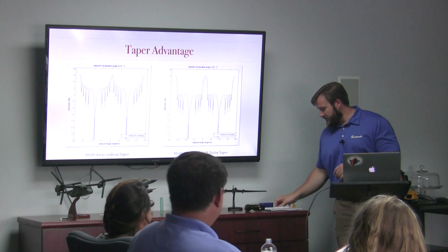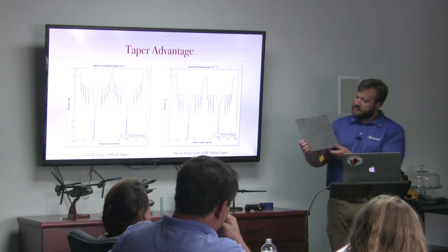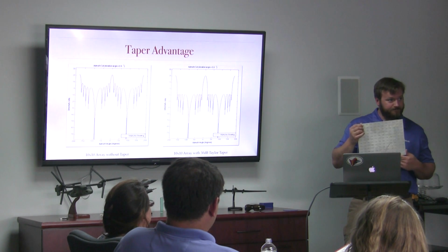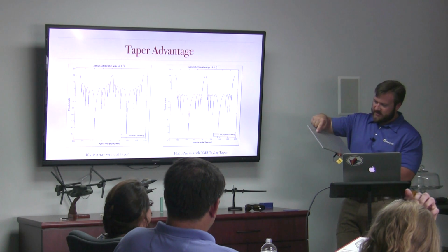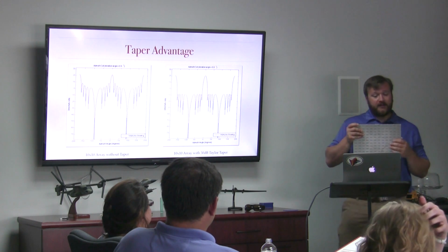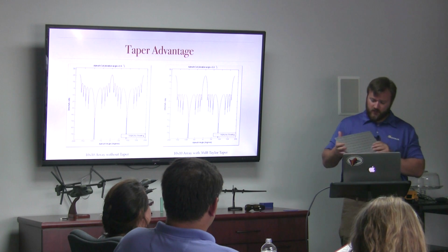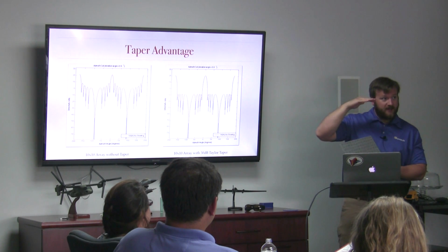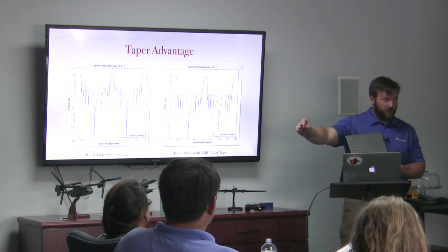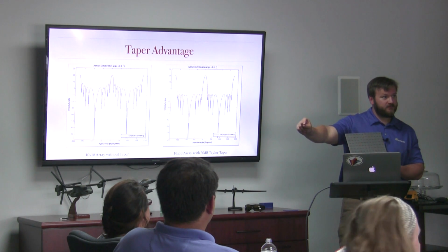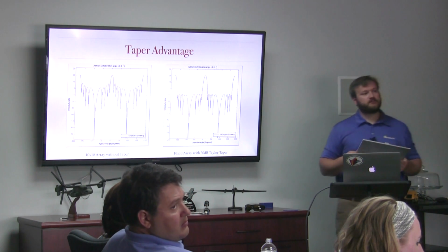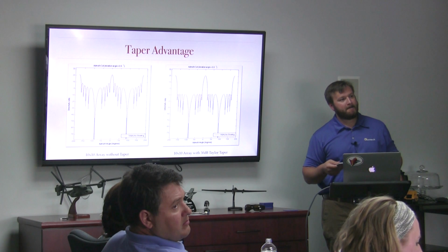Yeah, sure. Well, here's actually a prototype antenna that we worked with. And so we have the columns, we have the rows. Now this one is a uniform rectangular array, and we have them spaced and offset to get rid of some of the side lobes, or to pull some power out of the side lobes. Now on the antenna, the large array, we actually start out in the center with a larger magnitude taper that comes down, and it's using a Taylor series expansion to give us our offsets for that. Make sense? It's the amount of separation. The taper is how much the slots are offset from the center line, which is the greatest in the middle and goes down to nil at the end.